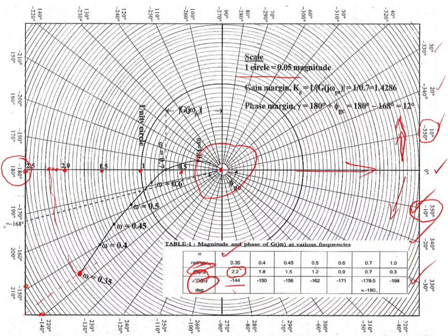So this line and this line, this is the point, this represents 2.2, and the phase angle is -144. The next one is 1.8, -150. We know -150, and 1.8 is after 2, at 1.95 and so on. Each and every circle is 0.05. When we are calculating, this is 1.5, and this point will be 1.75 at the center, and the next point is 1.8. So almost here, just take this, -150, 1.8.